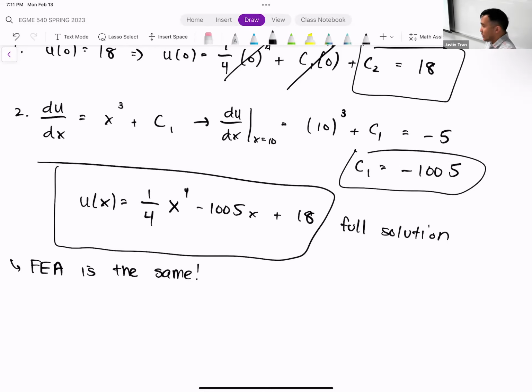In fact, and you may have tried this already in the first two activities, if you try to run a simulation without applying boundary conditions, ANSYS is actually going to give you an error, because what they've been telling you is that the problem is not fully defined, or it's not fully constrained.